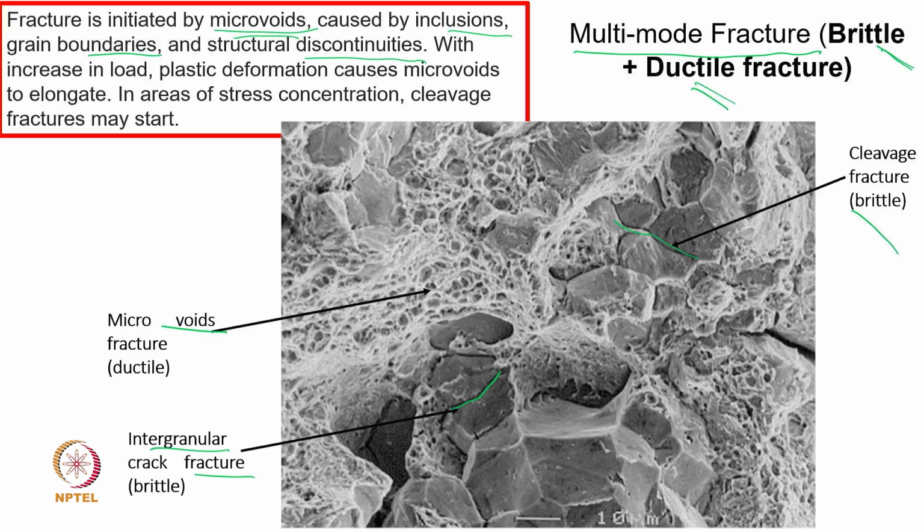Now, at a lighter load, microvoid formation will quite possibly occur, but it will not be sufficient for fracture or failure. But if the load increases and crosses the elastic limit, which was covered in previous lectures, then there will be some plastic deformation, which is continuous and irreversible.